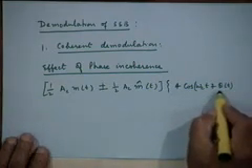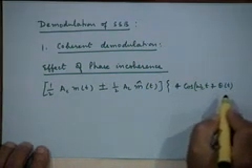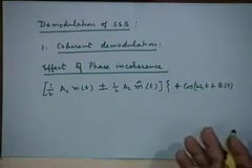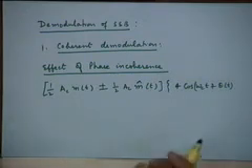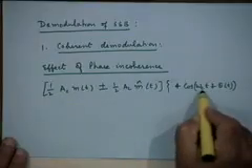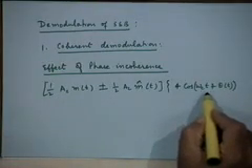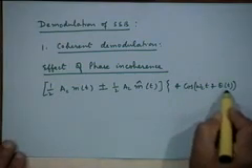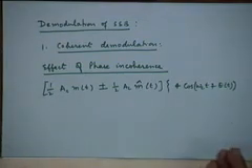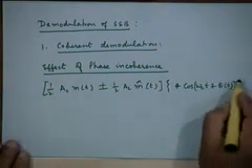In fact, let me consider this as a time varying phase offset, which can model both phase offset as well as frequency offset. A frequency offset, for example, is a time varying phase offset. So a more general expression is to write omega_c t, which should have been the true carrier frequency, plus theta of t, which models both the phase offset as well as the frequency offset.